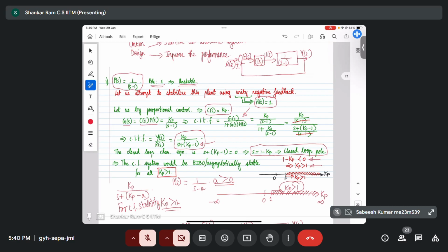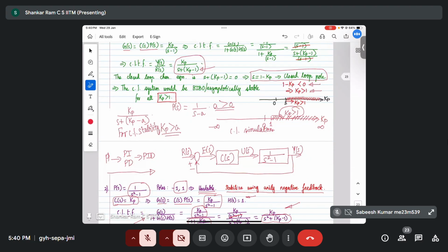Now, whether we will have an actuator in practice which will realize this control input is the next question. That has to come later. Okay, this is the first step. So what I mean is that once we design a controller, we do closed loop simulations. Let us say by doing closed loop simulations, you plot the control input u of t with a time axis. Let us say your actuator capacity is some 100, I'm just using a round number. And by extensive simulations, always your control input is within 100, then you are okay.